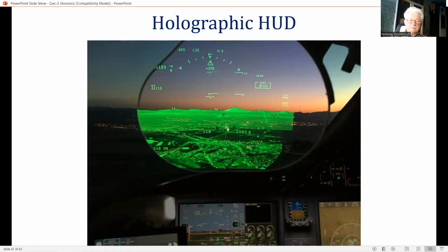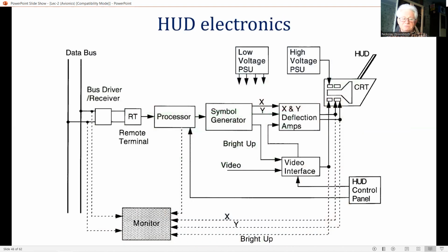Modern HUD systems are used as the prime display of primarily flight data such as height, airspeed, altitude, heading, and others. The HUD thus becomes a safety critical system when the pilot is flying head up at low altitude and relying on the HUD. Modern HUD systems for both military and civil aircraft are therefore being designed so that the probability of displaying hazardous or misleading information is of the order of less than 10 to the power minus 9.